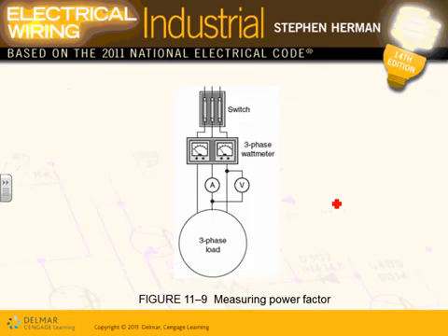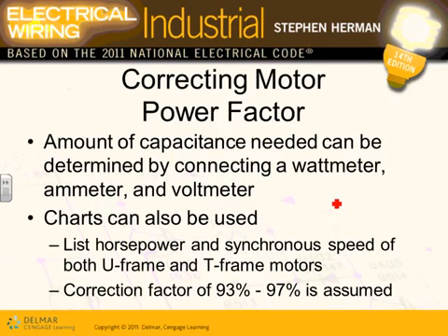Measuring power factor, we talked about, guys, measuring power factor. You need a watt meter and an amp meter. Typically, if you have a watt meter, amp meter and voltmeter, you can calculate it, or you can have a var meter and a watt meter.